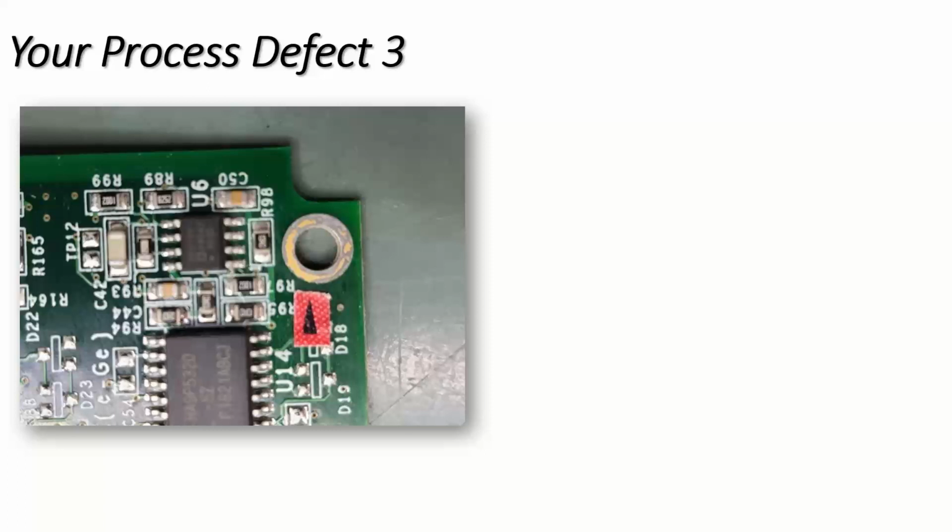It's a cosmetic defect, a process indicator, if you like, but provided it's not going to affect the functionality of the product, provided it's not going to stop the board from sitting correctly into whatever module, or it's not going to affect putting a screw or nut or a bolt or a fixing in this hole, then really it's cosmetic. And yes, the contractor should do something to improve the process which has allowed this to happen.